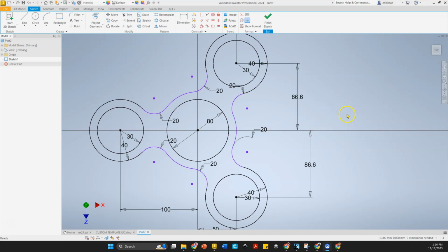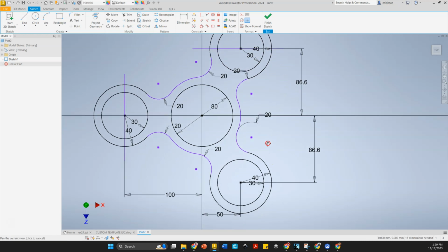So now we've got to cut the circles on the outside like the example. Click your line tool, line it up with the center of the circle so that you get the little extension lines off of there, and draw a vertical line there. Repeat the process. This one's going to be a horizontal line just right at the halfway point for each of those, and then this one here too.